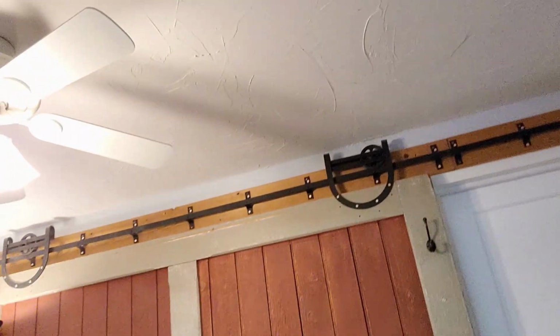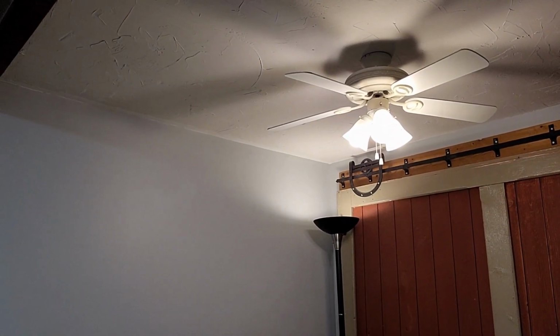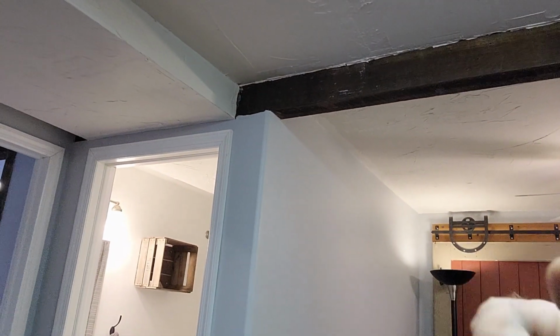Then you go around back and you'll see that the house is actually 3 stories deep, where 2 stories are completely buried into the hillside, and you've got 3 exposures on the backside of that building. They are literally building their homes into the sides of a mountain. It's actually pretty amazing to see, but you would want to know that whenever you're going in, because you're not going to treat that basement as a completely dug in basement, and you certainly wouldn't treat it as a complete exposure. So know what you're dealing with there.